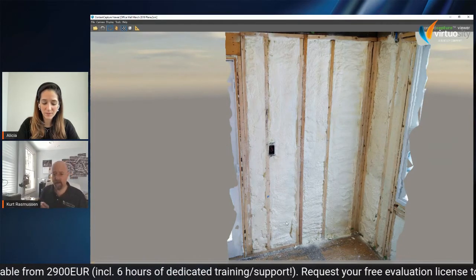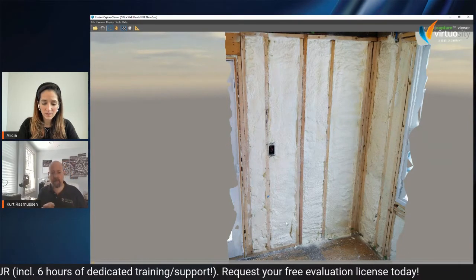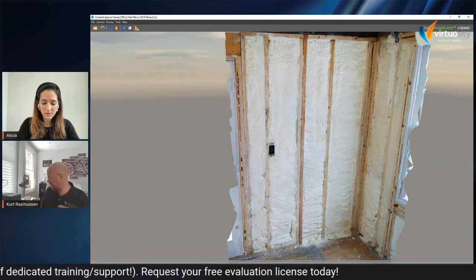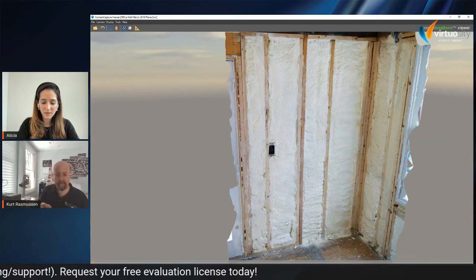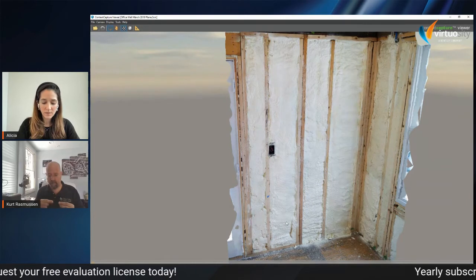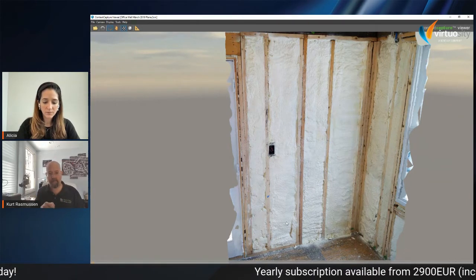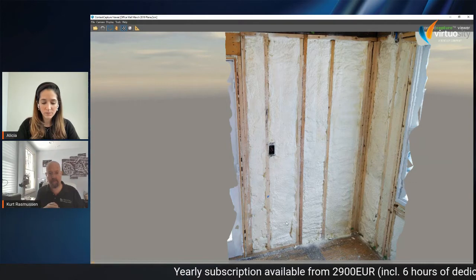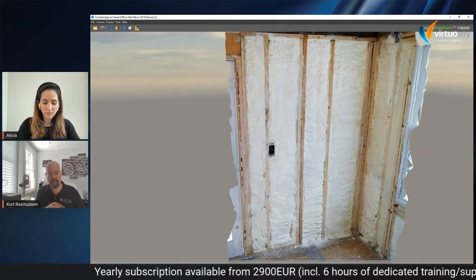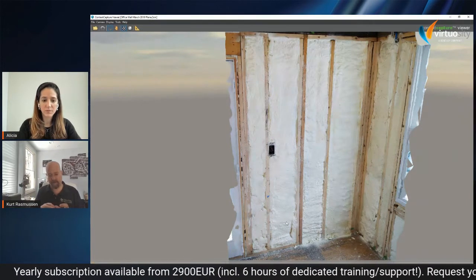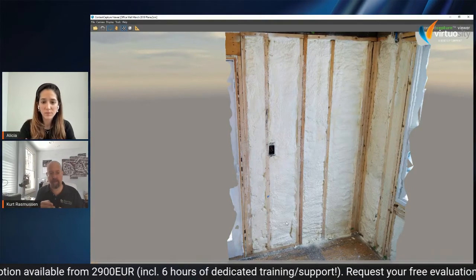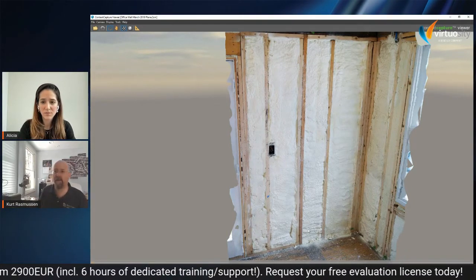I'm sitting there, and really how this worked out was I was taking measurements. I had this metal poker. I actually have it somewhere here. This metal poker that I put electrical tape 3 inches up on it. So this way I could punch it through the foam till it hit the board behind it, and then I could see if I hit that mark, which means I have 3 inches of foam. But I'll get into the R values then.